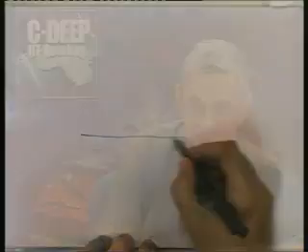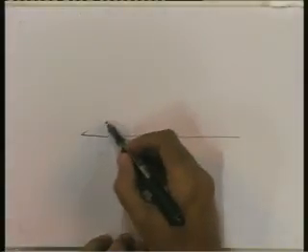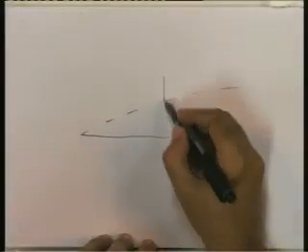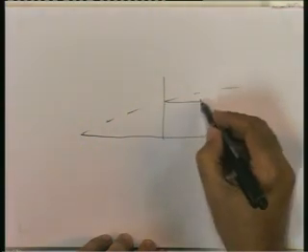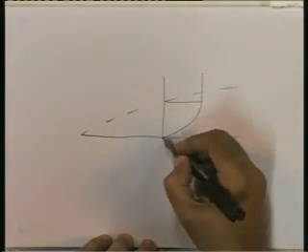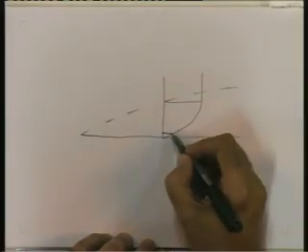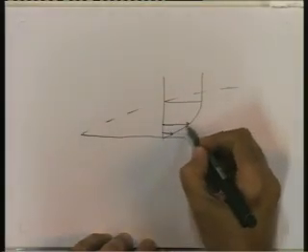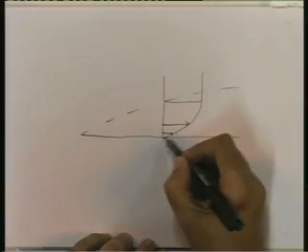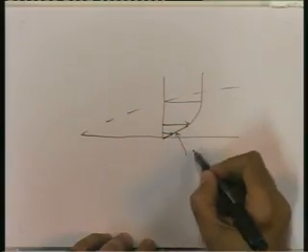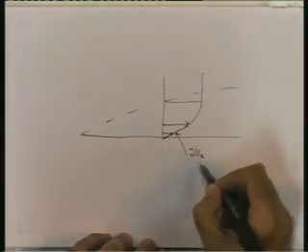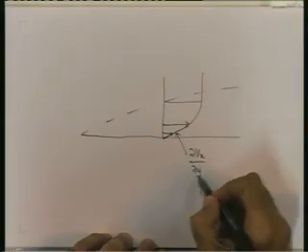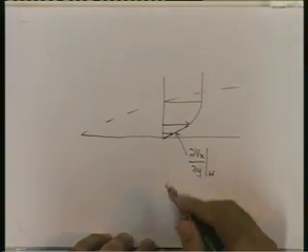Let us look at the definition of the drag coefficient. If we have a boundary layer, this is the velocity profile in the boundary layer, and because of this gradient of velocity at the wall, this slope represents the variation of Vx with respect to y at the wall.